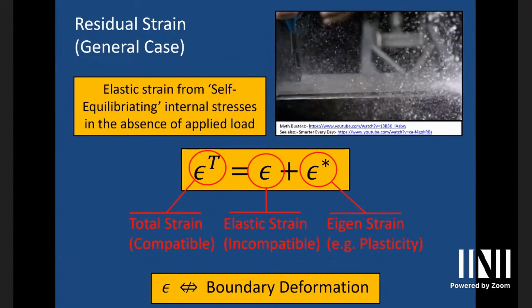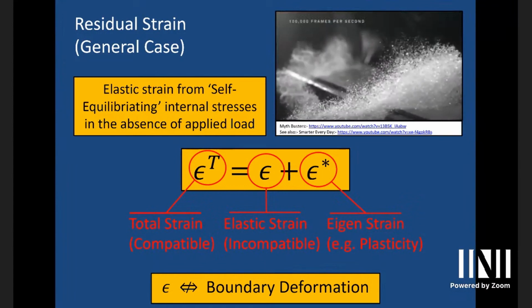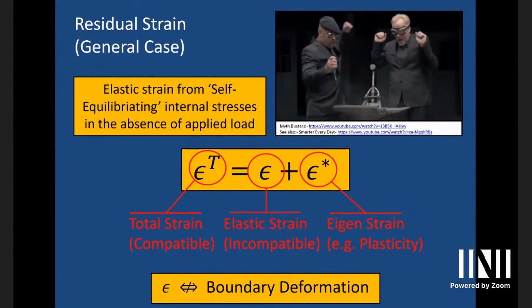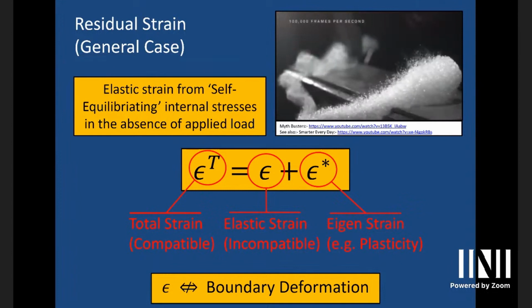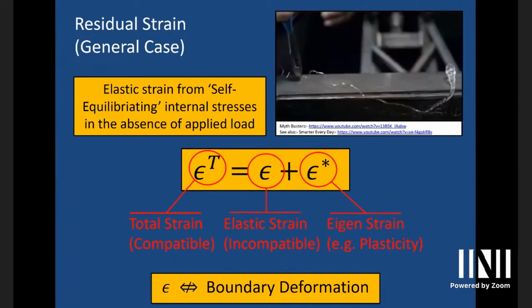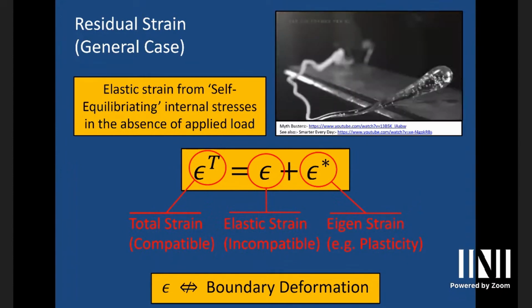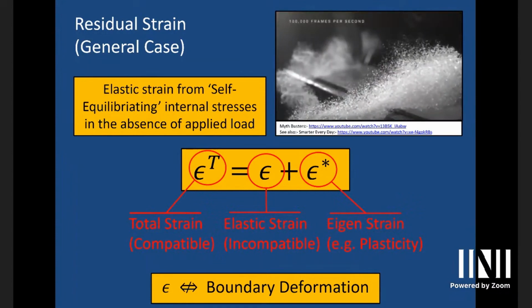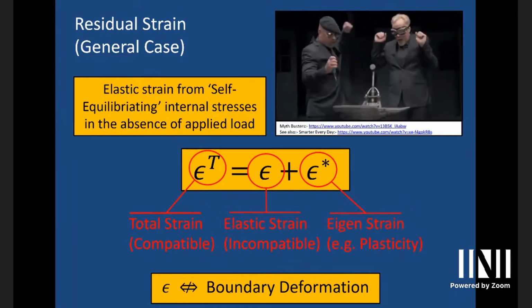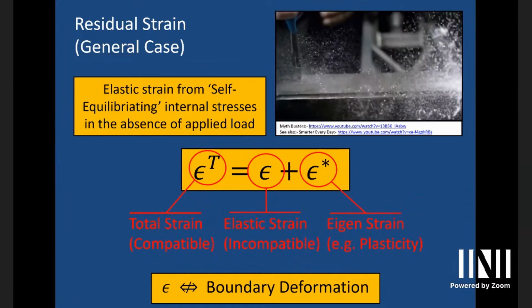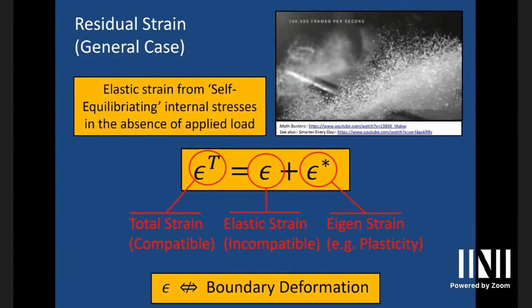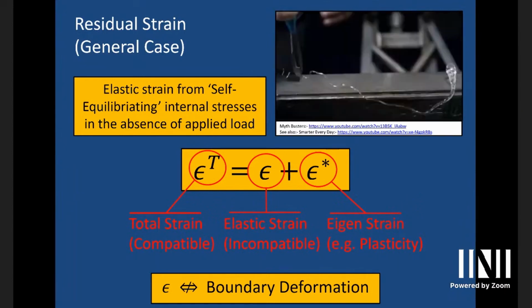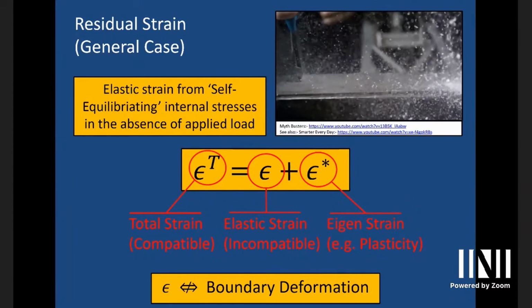So if we've got plasticity in metals, it's usually due to just moving the lattice over one atom through lots of different mechanisms. Plasticity doesn't change the lattice spacing. Right? What we see is only the elastic part of strain that's related to the stress that we're applying. Like sliding? Yeah, exactly. That's exactly what's going on. The planes just slide; they don't get further apart from plasticity. And so we measure this one, right, which is inherently incompatible, so it's not related to boundary displacement. So we can't do that same trick. So we need a better approach or a different approach.